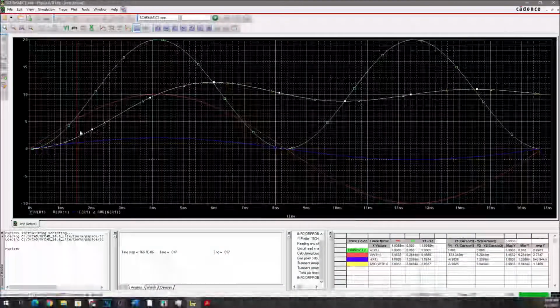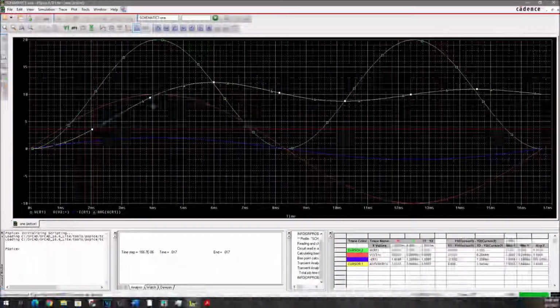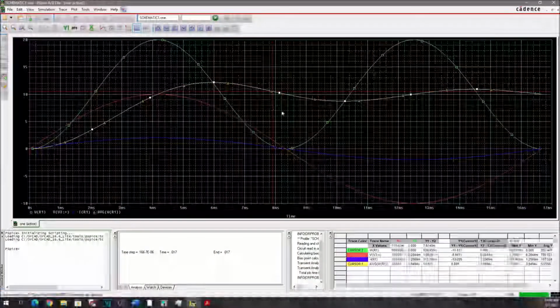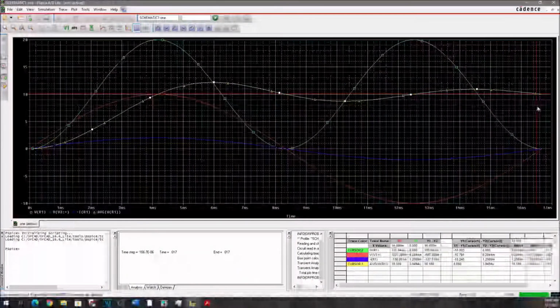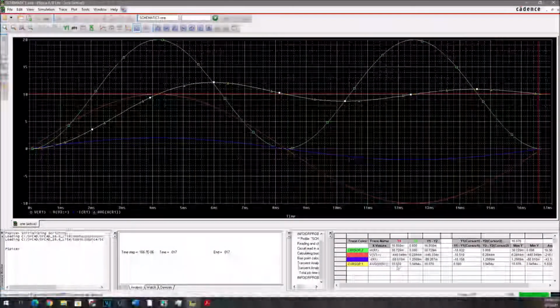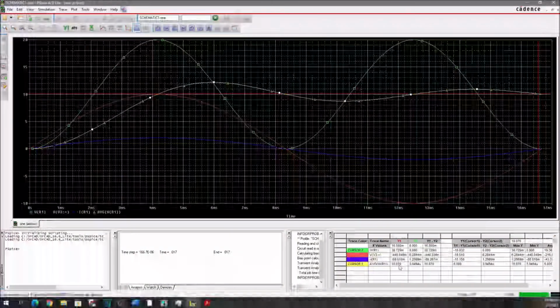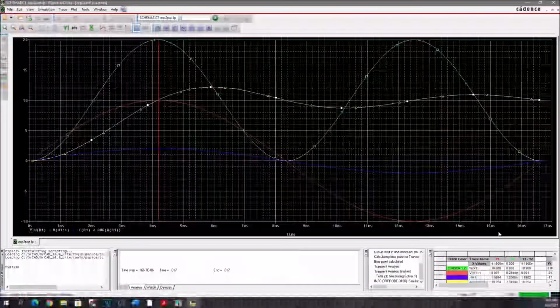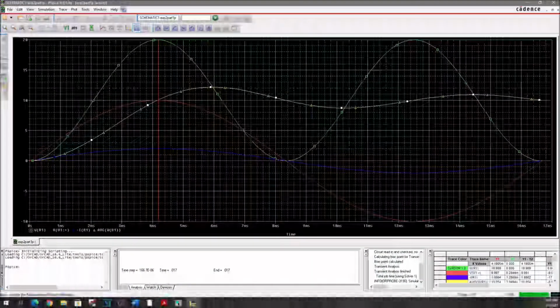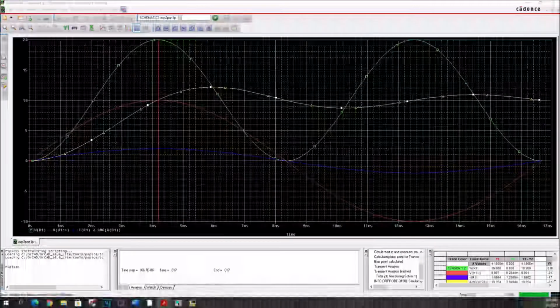To measure the average power, let's click here. Then, we'll measure the value at the end of its waveform at the stop time. So the average power is 10.070 watts. To test our measured values, we can calculate the theoretical values based on the given circuit.